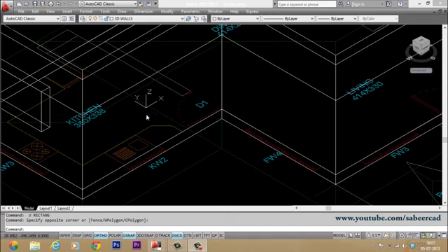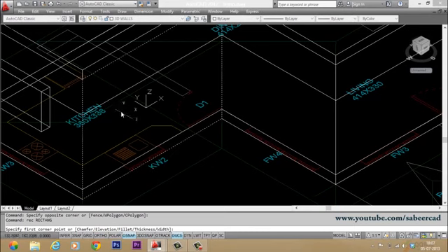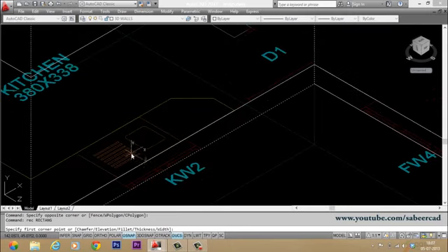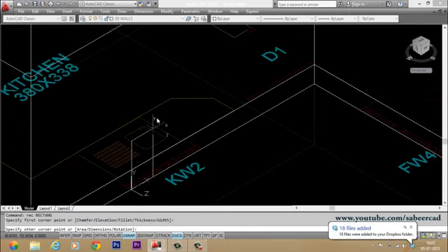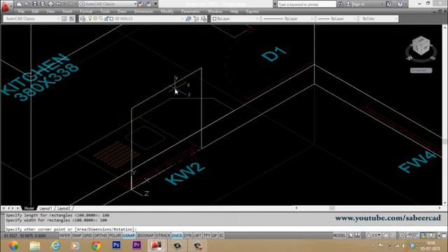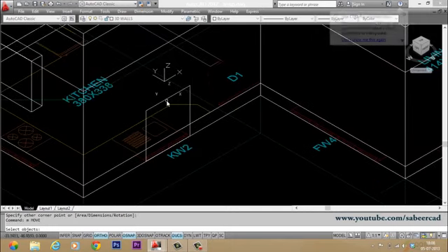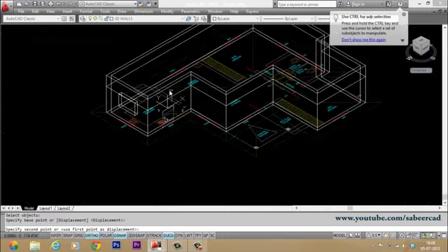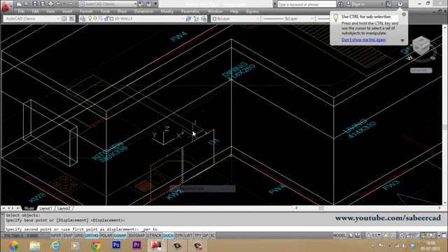Now let's create a cutout on this face. So I'll start with the rectangle command. I'll highlight this face because this is where I want the rectangle to appear. Now take the cursor on this corner and you can give the dimensions. Go to dimensions and you give a width of 100 because it's a 2-panel window and height of 100. Just fix the opposite corner here by clicking. Now move. This is the base point and you select the second point at the lintel level.